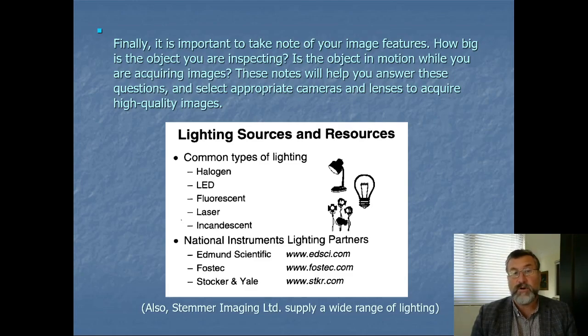But generally speaking, we're moving a lot away from that. And generally now, the lighting in machine vision is dominated by LEDs. And there's a number of reasons for that, which I could go into in a bit more detail. The most obvious one is that LEDs are very flexible. You can turn them on and off quickly. They're very efficient, so they don't heat up so much, so it's not such a waste of resources. And they generally have long lives as well, compared to halogen lights.